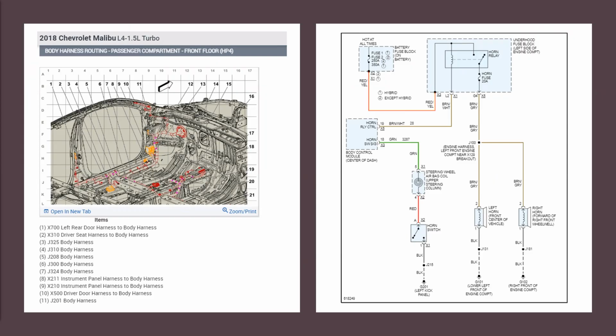And remember, the wiring that's up under the dashboard that's bolted into the firewall isn't as susceptible as the wires that are running across floor panels, like in that area, or door hinges. And then we take a look at the electrical map. Now, remember what the dash lines were when we started to talk about schematics. That means that component was actually part of a larger component. And we'll get into that a little bit more here in just a second.